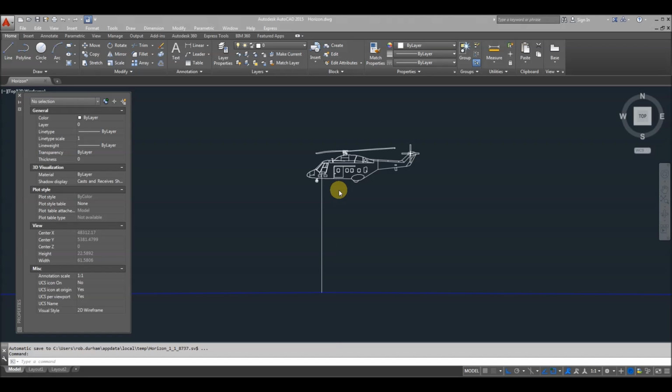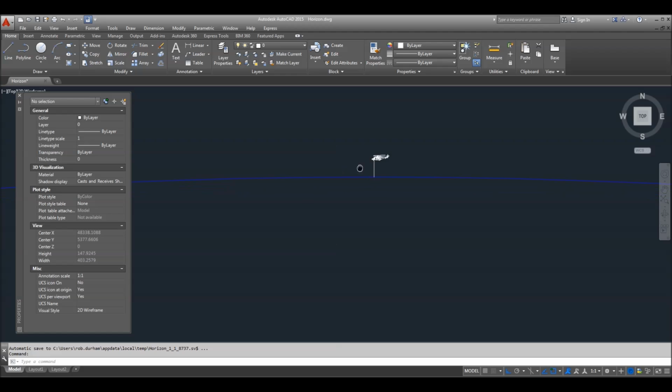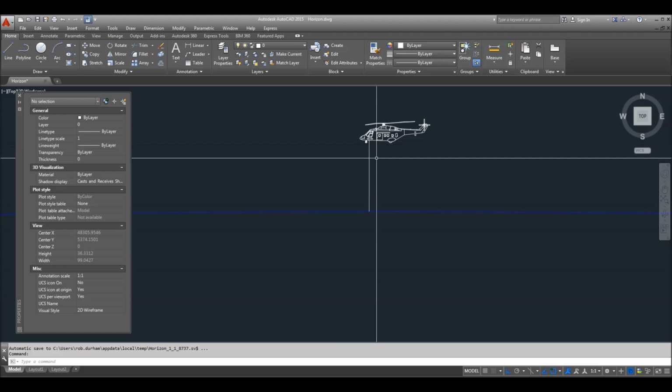But this doesn't necessarily mean that once he transitions from the hover into forward flight, that the artificial horizon is going to suddenly shift and drop to point at the true horizon in the particular direction that he is travelling at. It doesn't work like that. Although all indications and all external sources seem to suggest it should.